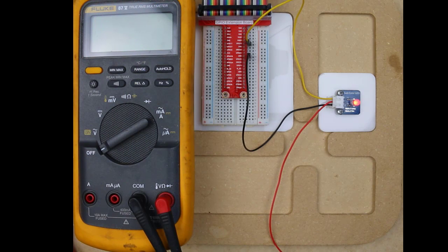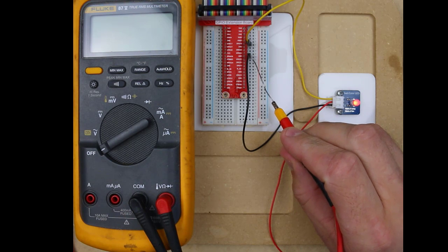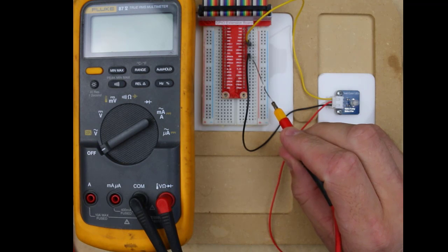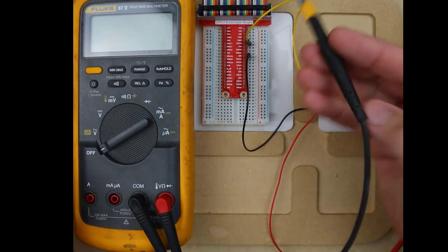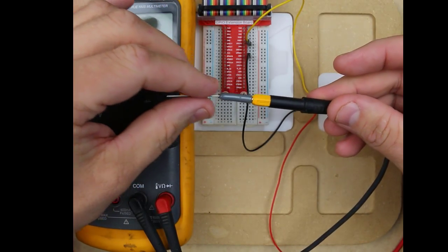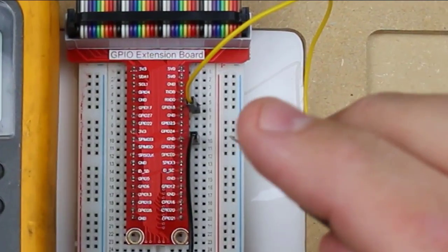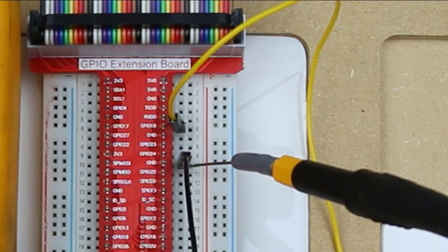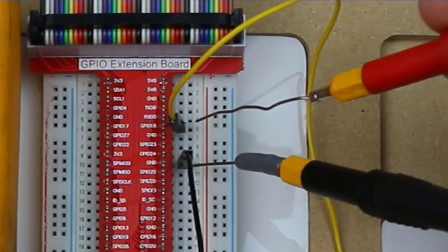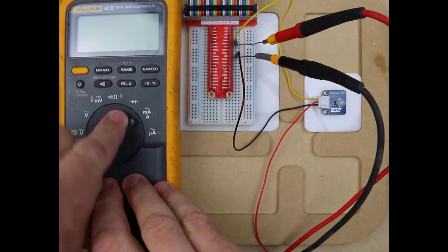We will now be making some measurements with the multimeter. You may or may not have to move over your GPIO extension board in order to expose at least one more pin. That extra pin is where we'll be connecting the multimeter. We'll take our black multimeter lead. Notice that I have this Fluke extension on there that just makes it a little easier for me to push down into the breakout board. I'm going to push it into the breakout board at the ground pin, so it should be matching right against the physical pin number 20. My red meter lead will be placed in the physical pin 12, GPIO pin 18.